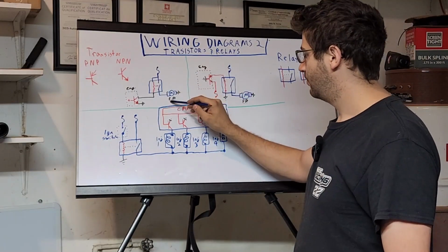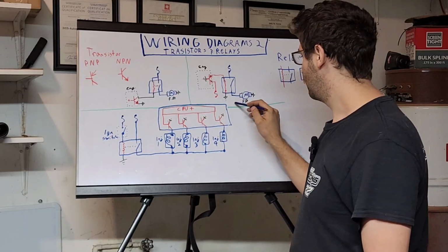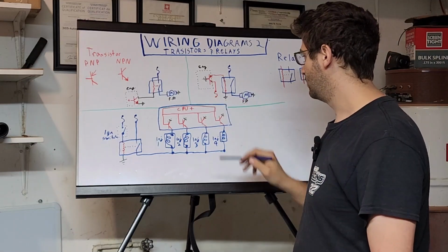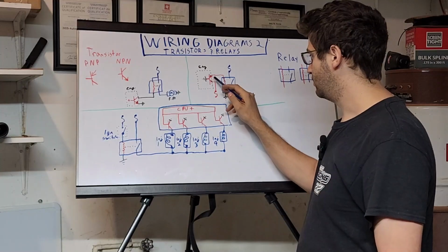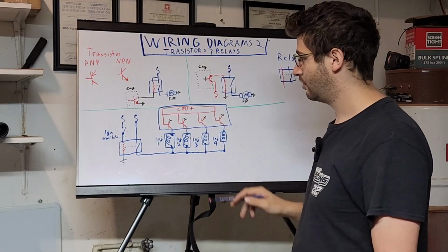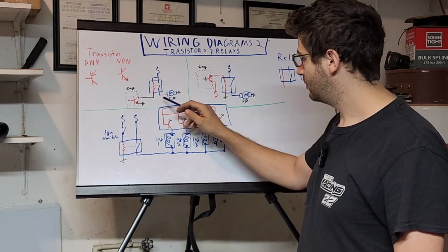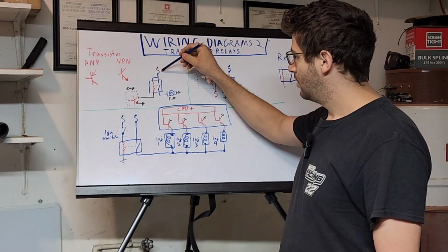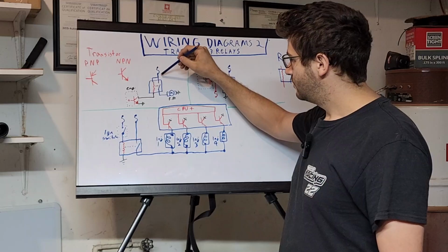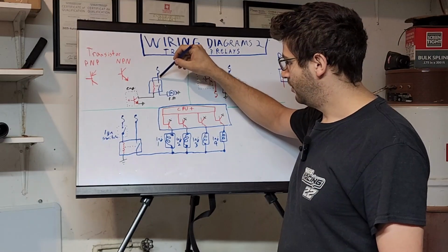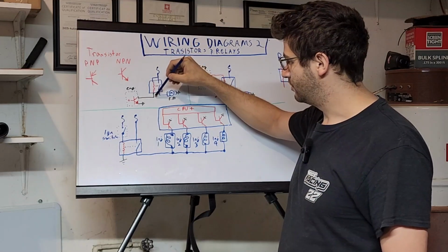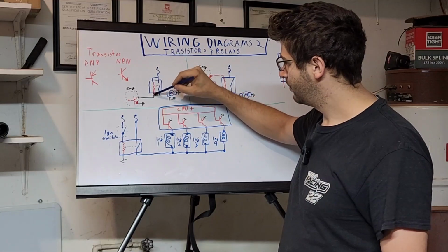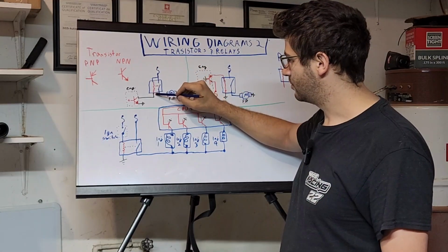Here we have kind of a basic fuel pump circuit, 2 ways to do it, whether it's a high side driver or a low side driver. Low side's more efficient. They tend to last longer. So we have a fuse powering both sides of the relay, and the transistor is going to control the ground side of the control of the relay.